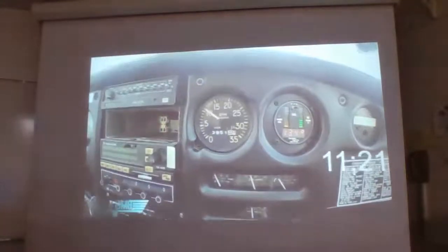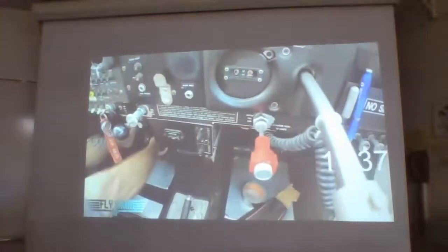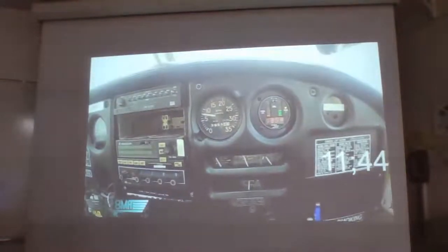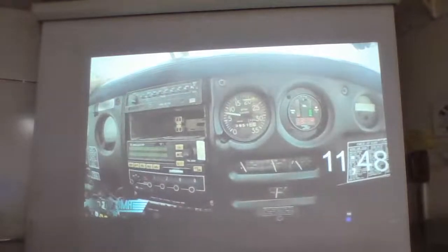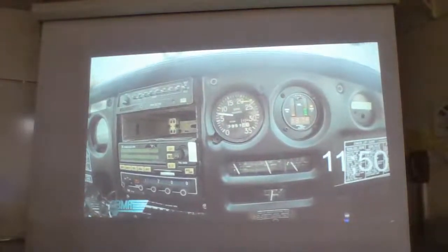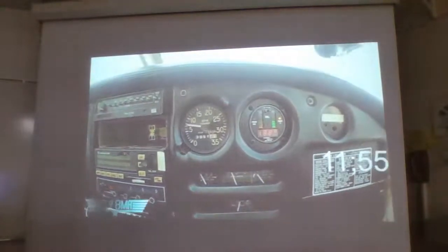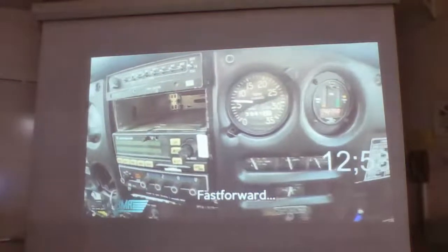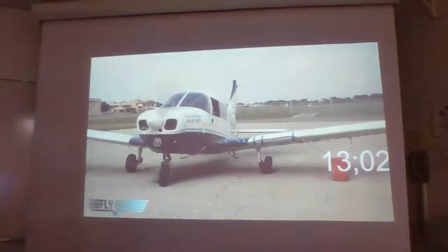Yeah, I think this might finally be it. Oh, there's 1,000. So we're just down to idle. We got full power set here still. Normal mixture setting. I don't know what else to do. Fuel pump on, guys. And we're down to probably about 30 pounds of thrust is all we're getting out of this thing. 40 pounds of thrust down here around the 700 RPM range. 138 degrees. 700 RPM. It feels like something's ready to snag and break in here. Really feels like something wants to break.